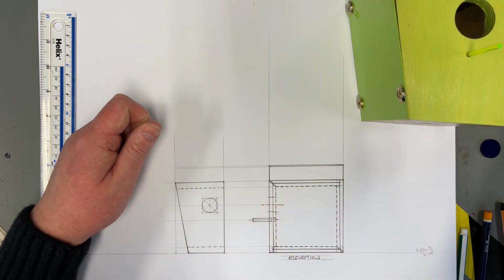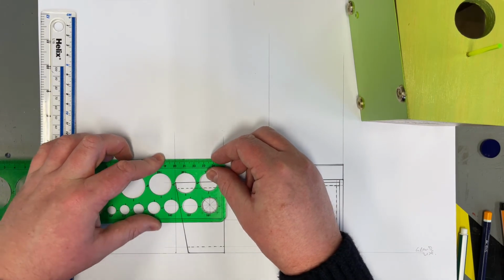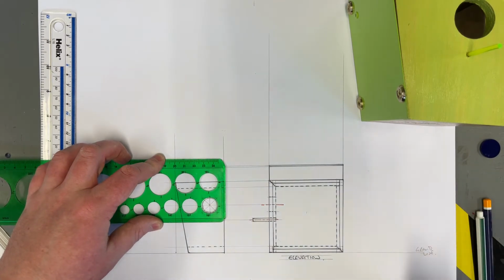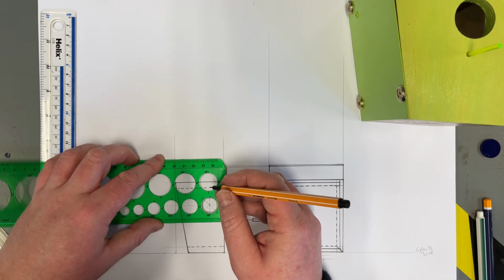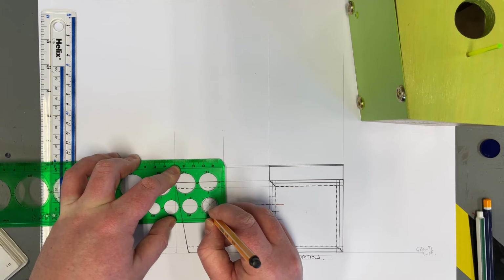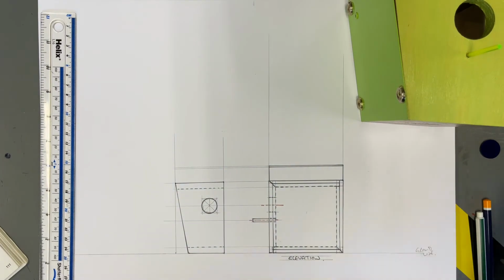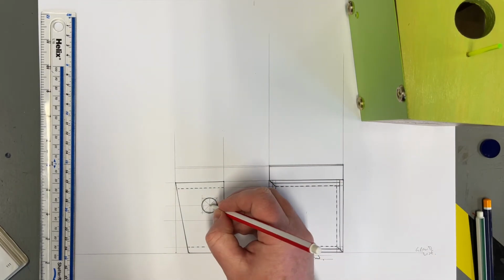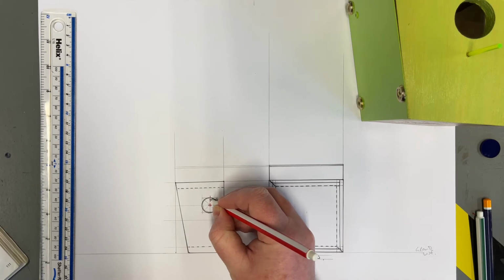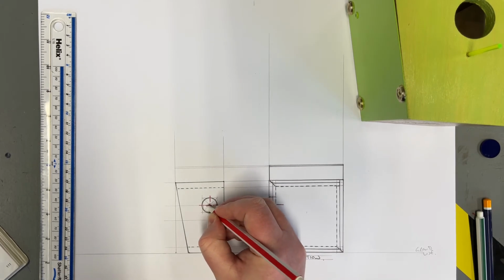Or the other way, if you've got one at home, you could use a circle template if you want to get it a little bit neater. Okay, circle template. Just be careful if you're ever using pen. The pen can allow the ink to run underneath the circle template, and sometimes that bleeds over your paper, so you might be better just to do this bit by hand. To show that that's circular again, you'd have your center lines in, short dash, long dash, and just have those projecting through the circle, tops and bottoms.